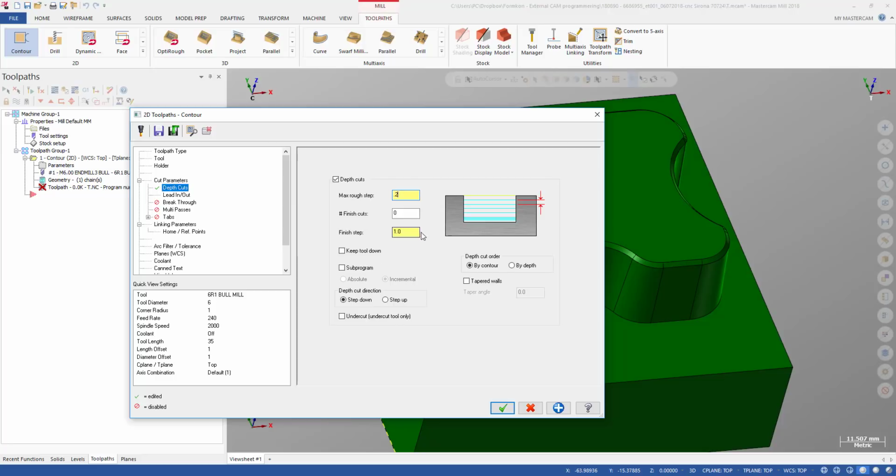And I'm gonna select keep tool down so we can avoid the tool retraction, and we go for the trick here. You will see an option called taper wall, and when we click on this, we can use the 2D contour for machining the taper wall on the part.